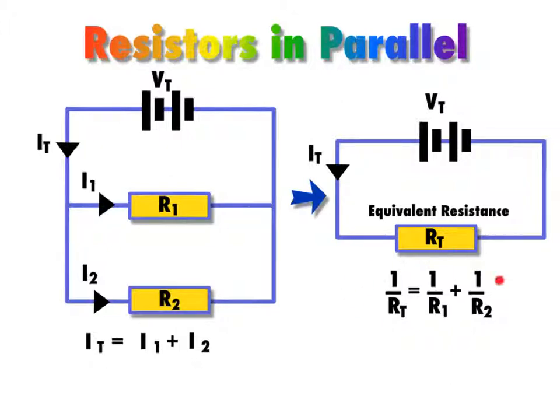So this kind of a problem usually involves you finding some common denominator on the right hand side here, adding the two resistances, remembering then that that is a value for 1 over RT, and when you get your final value, flipping it, inverting it to get a value for RT. And this will become more obvious when we have individual numerical values.